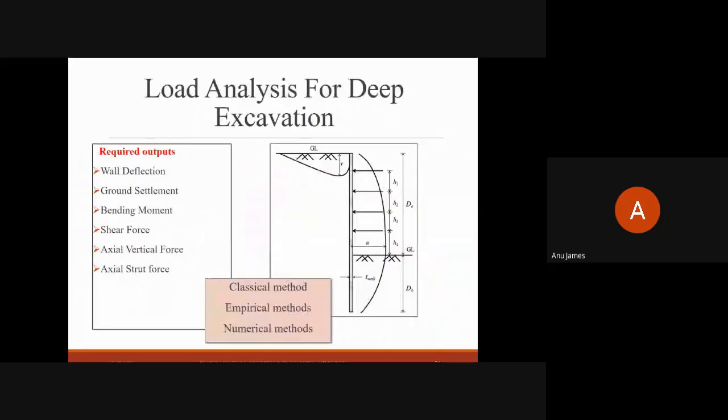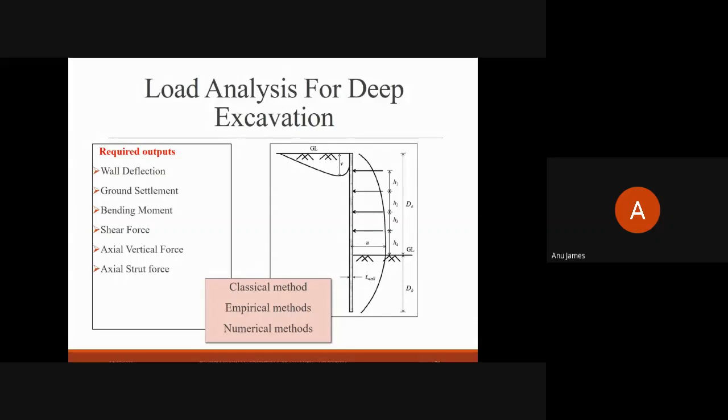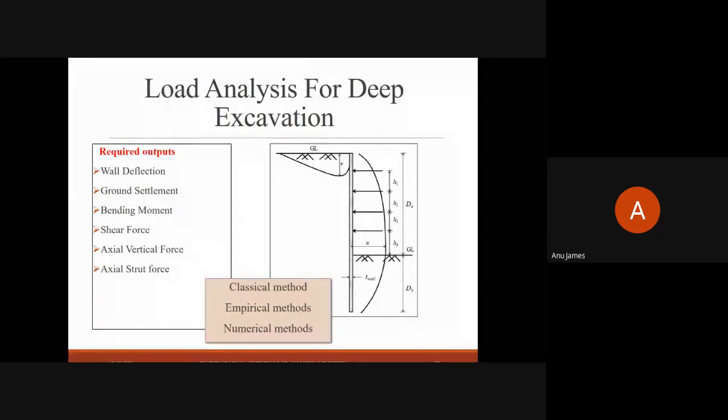So from load analysis of any deep excavation system, either supported by a diaphragm wall or by any other sort of retaining structure, these are the different outputs we seek: the deformation of the wall and ground, or other forces which are developing on the system, such as bending moments, axial forces on the wall, shear forces, and the forces developing on the supporting structures. To analyze these, different classical, empirical, and numerical methods are currently available.